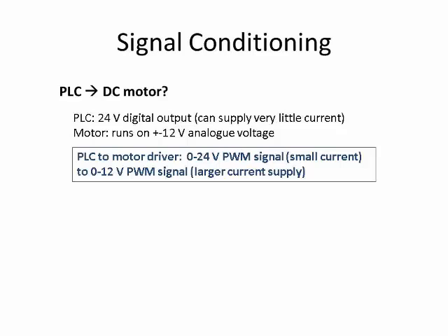We supply the motor driver with a pulse width modulation, or PWM, signal from the PLC. The PWM method allows us to make a digital signal appear as an analog signal by switching between 0 and 24 volt at a very high frequency. The motor driver then scales the signal from the bench power supply according to the PLC's PWM signal and feeds it to the motor. The bench power supply is then actually driving the motor, and it can supply enough current to meet the motor's requirements.